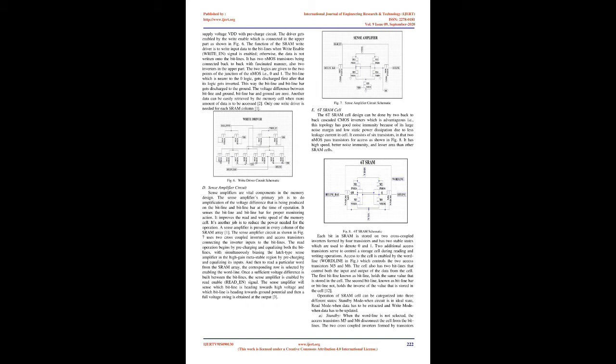The 2:4 decoder truth table is given in Table I. Circuit schematic and simulation waveform are shown in Fig 4 and Fig 5 respectively. Write driver circuit. The driver circuit, also known as a write driver, is one of the basic components in the memory design circuit. The job of the driver is to bring the bit line and bit line bar to the ground potential, which are initially charged to maximum supply voltage VDD with the pre-charge circuit.